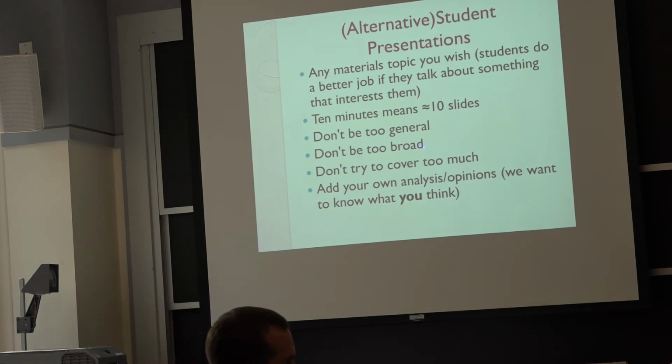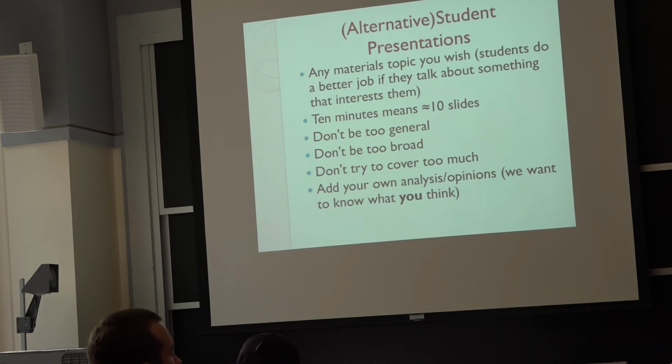One student actually came back from Yokosuka where he had a tour, and they had opened up the seawater tanks on some ship to inspect them, and they were all corroded. It was a type of corrosion no one had seen before. People came over from NAVSEA, David Taylor, the corrosion experts came over. They couldn't tell what it was, and when he left, they still didn't know, but they knew they had to get people in there scraping it, painting it. So they did that. But he had pictures of it, and it wasn't classified, and he showed them to us, and we discussed what we thought it might be. I think it was probably what's called microbiologically induced corrosion, where bugs start generating acids that eat away your tanks. So it depends on what you put in your tanks.